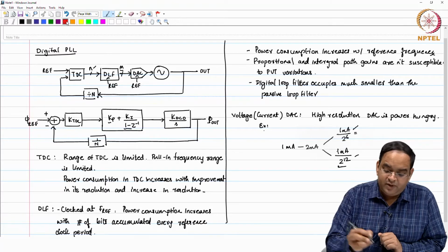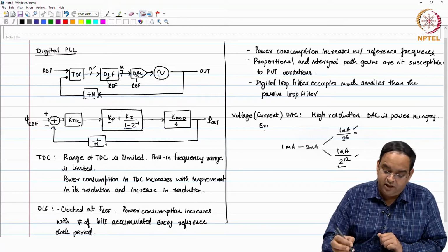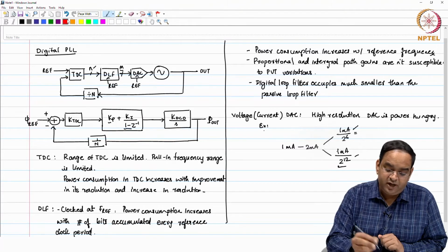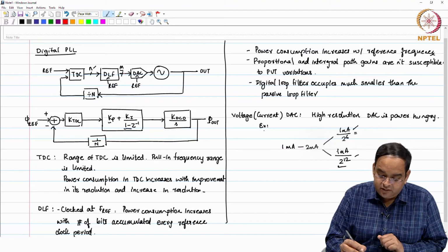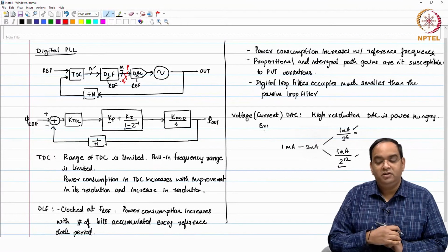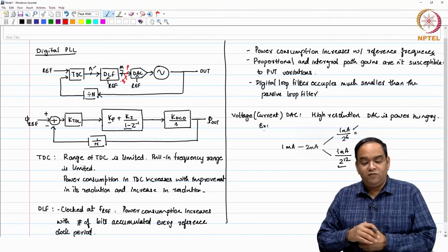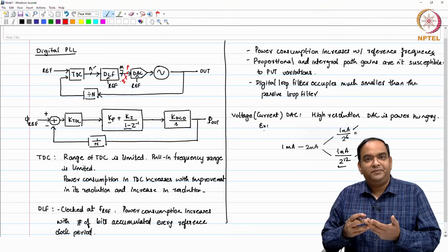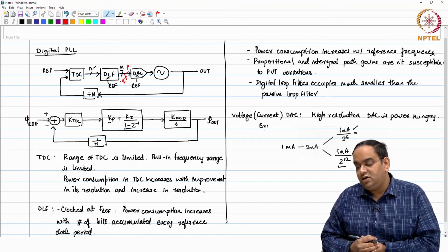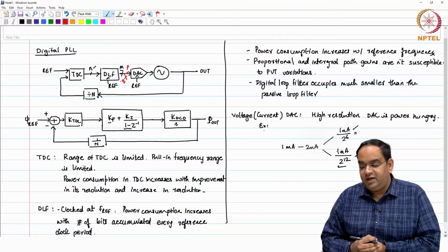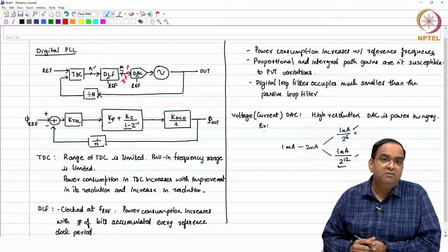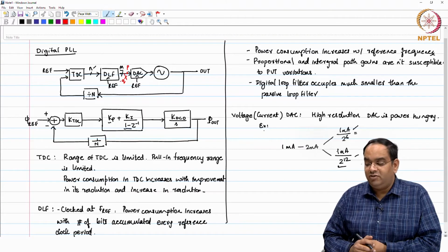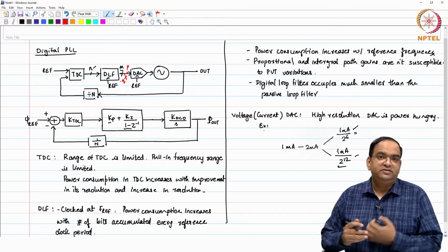So, what happens normally is that these m bits which you have are not fed directly to the DAC. You have p bits here and you have q bits here. So, you have a gain factor involved here. You want to control in steps of 1 milliampere by 2 power 12, but you are controlling by 1 milliampere by 2 power 6 in that resolution.